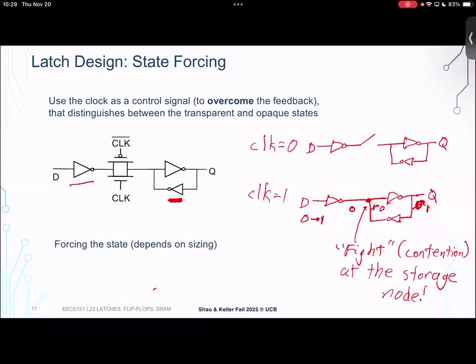So this is very unlike any other CMOS gate that we've had before, because it is not contention free, which was another nice property of all of our CMOS logic. So you do still see this design style used sometimes. The advantage is that it saves you transistors, it saves you area. And flip-flops are so common that sometimes it's worth being a little more aggressive with the design. And as long as you're very careful and simulate it all different kinds of ways, you can convince yourself that it's going to work reliably.